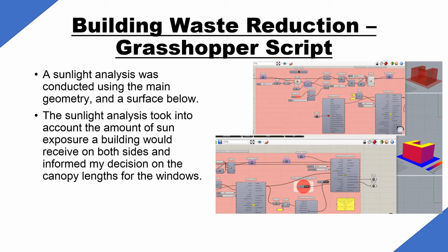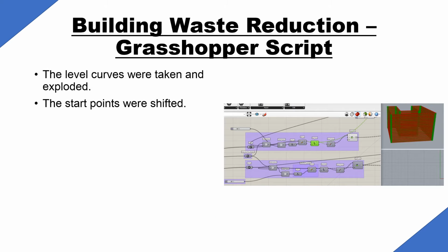A quick Ladybug sunlight analysis was also done, and this was to find how the sun reacts within the Sydney area. This would allow me to consider where the canopy lengths on each of the windows have to be longer and where they can afford to be shorter. Level curves were taken, exploded, and shifted for a later step.